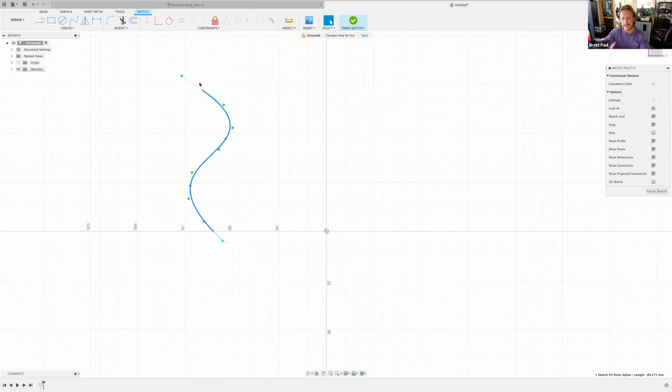So if you look at a specific point, you have angle, magnitude, and the points X and Y locations. Okay. So you have 4 different things about each point on a spline. So that for us right here is 16 different points that we have to consider when we fully define this thing. So I'm going to go ahead and start doing that.